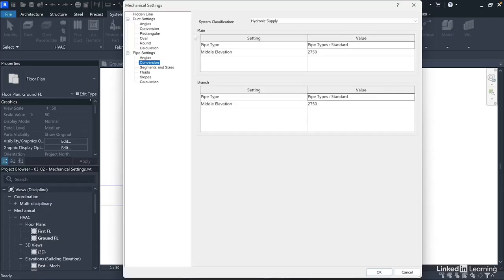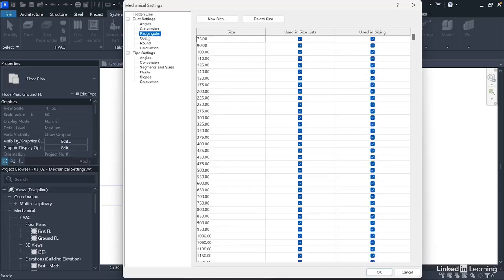So you can see it's literally the same settings. Of course, when it comes to ducts, you also need to specify the flexible ducts if you're using that to finish off your system, and also the maximum flexible duct length, which we'll still look at much later in the course. Then the next we'll have is the sizes for the ducts.